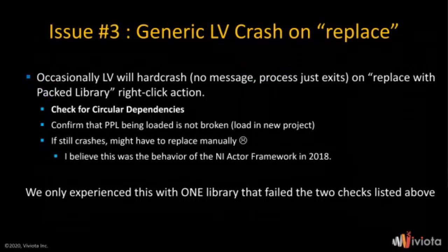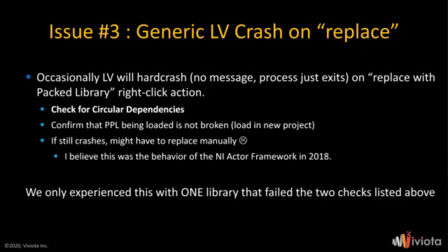We found lots of LabVIEW crashes. One of them happened when we would right-click and do the replace with PPL operation, and LabVIEW would just crash. Hard crash, no message, nothing. Sometimes this was because of circular dependencies. Sometimes it was because the PPL was broken, which can be validated through unit testing or just loading it into a blank project and seeing what happens. And sometimes it just happened. I think this is what happens with the anti-actor framework in 2018 as well, and in that case, we just had to do a manual replace.